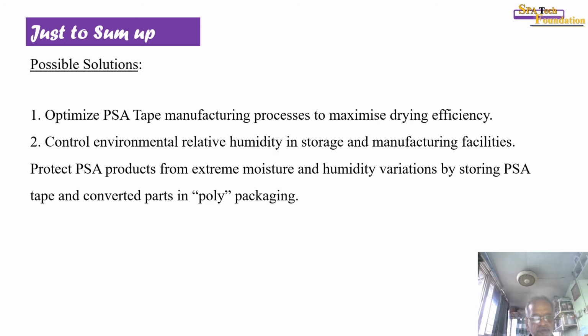Possible solutions: optimize PSA tape manufacturing processes to maximize drying efficiency, control environmental relative humidity in storage and manufacturing facilities, protect PSA products from extreme moisture and humidity variation by storing PSA tape and converted parts in poly packing.